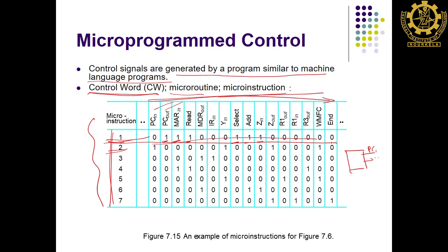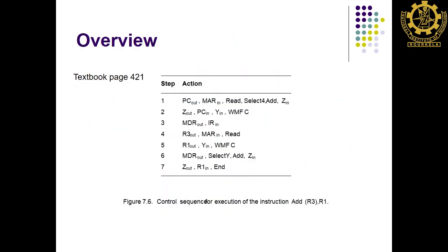After reading this part, next, consider what happens while executing a program. The program counter is incremented one by one to get the next instruction. Here also we should have a counter, to distinguish it from the original program counter we call it the microprogram counter, and that will be there within the control unit.